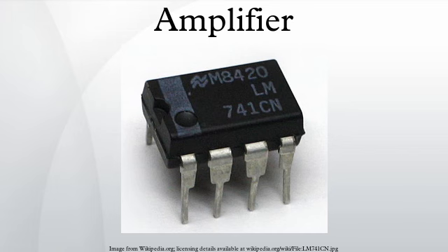The letter D used to designate this amplifier class is simply the next letter after C and, although occasionally used as such, does not stand for digital. Class D and Class E amplifiers are sometimes mistakenly described as digital, because the output waveform superficially resembles a pulse train of digital symbols, but a Class D amplifier merely converts an input waveform into a continuously pulse-width modulated analog signal. Additional classes: Class E.